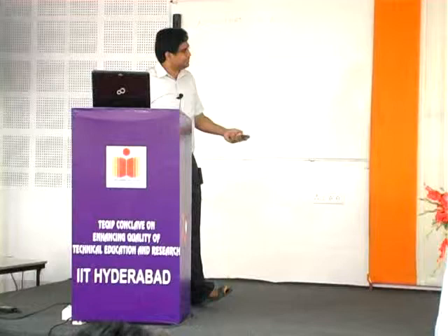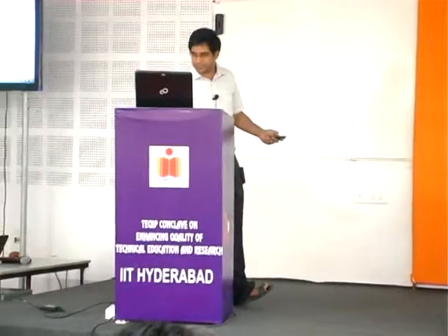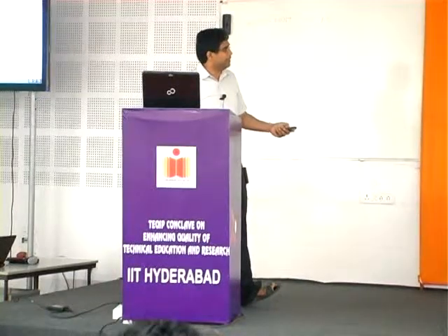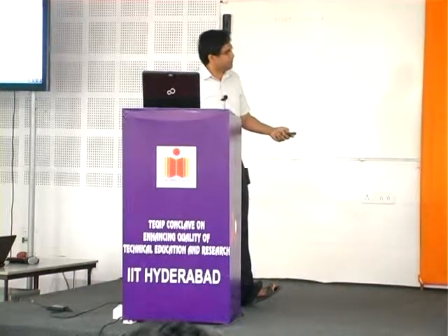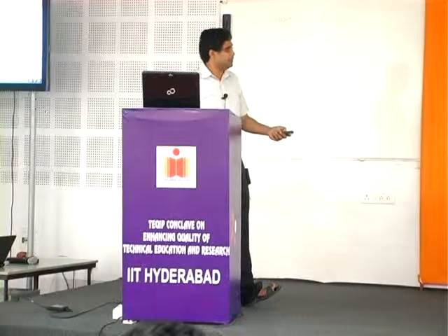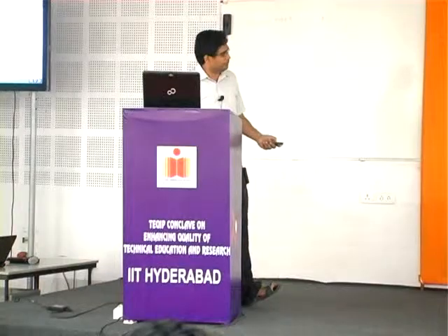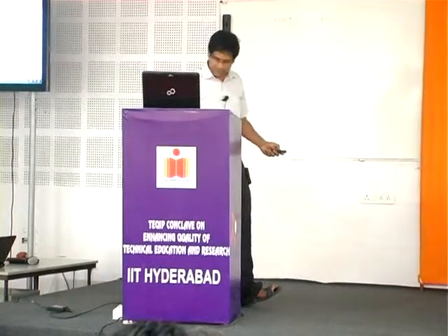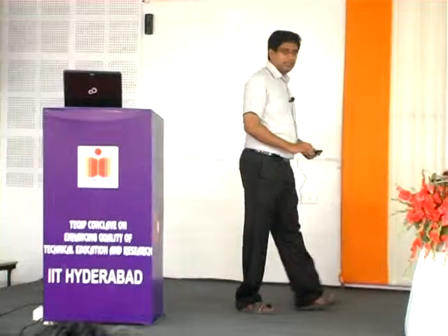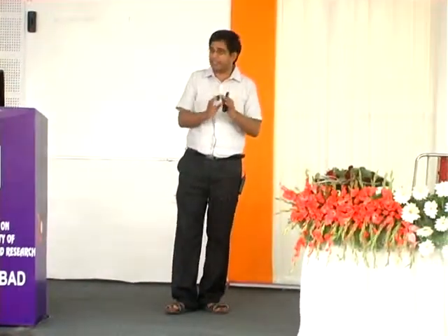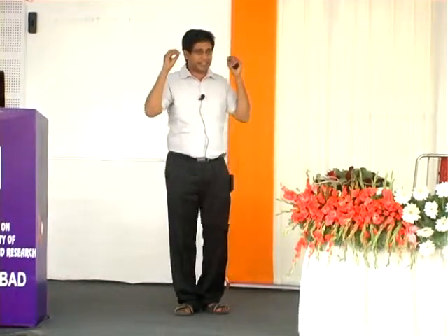We have similar process steps involved in this process. Here you are trying to convert an N region into a P region, so we use a diffusion furnace, again the same instrument. And then after that we remove the protective layer. In essence, what I am trying to get at is, if we envisage a device that we want to fabricate, we have all the facilities that are required to get the device into working condition. So we have the capability.